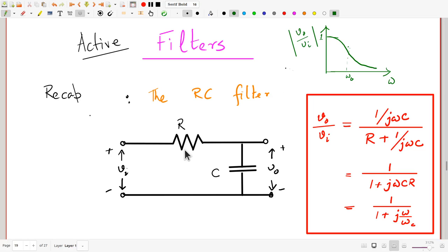And if you were worried about having a large source resistance or a tiny load resistance, you might very well use buffers using op amps, which we have learned about, to isolate the filter from the signal on the one hand and the filter output from the actual load on the other. So that's one way in which op amps can be used to improve the action of a filter circuit.